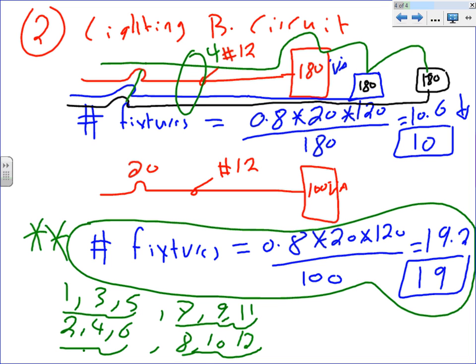Rule of thumb is you don't want more than 5 whips coming out of a J box. Right, 4 to 5 whips. So you do your math. If I want to put a J box right in here to feed these, there's 1 whip here, 1 here, 1 here, 1 here, 4. And a conduit coming in, conduit coming out, go to the next, have another J box, 4 whips, and you keep going. Does that make sense?